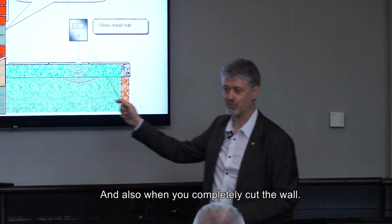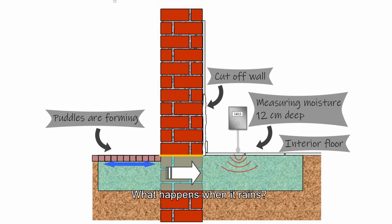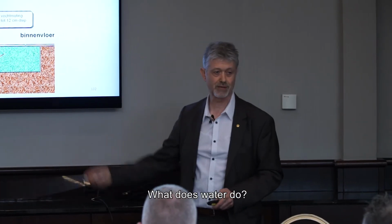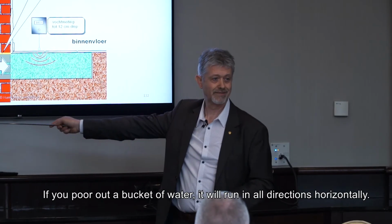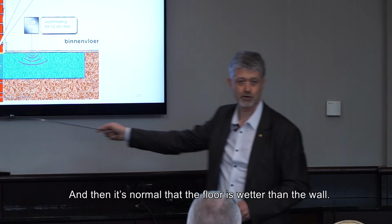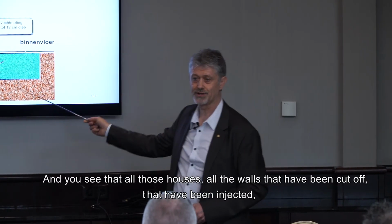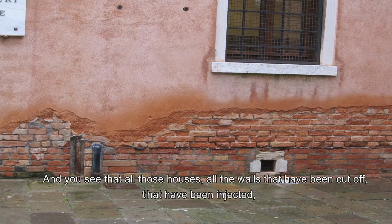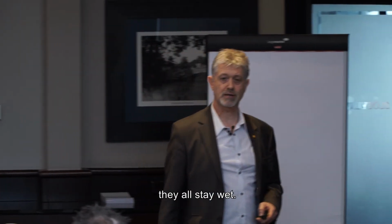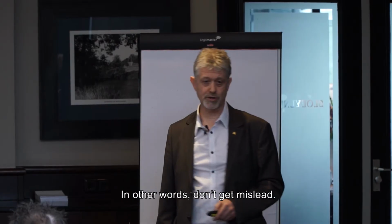And also when you completely cut the wall, make a cross-sectional drawing, let the water run, what happens when it rains? The ground level zone saturates. What does water do? If you pour out a bucket of water, it will run in all directions horizontally, and then it's normal that the floor is wetter than the wall. And you see that all those houses, all those walls that have been cut off, that have been injected, they all stay wet. In other words, don't get misled.